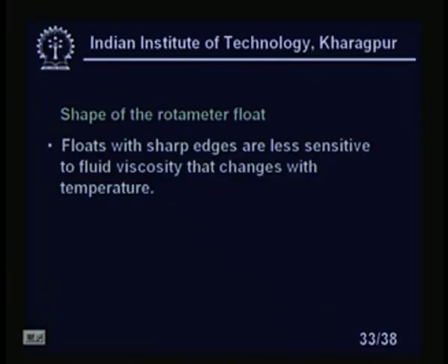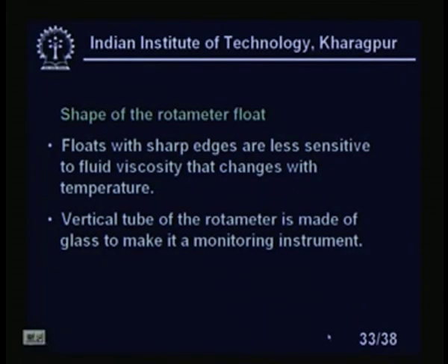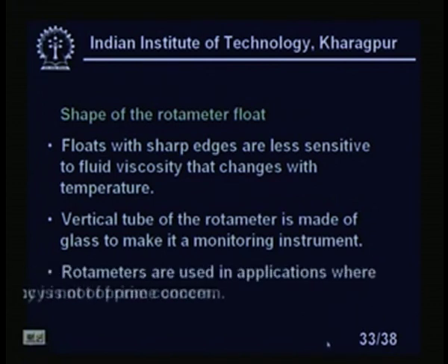Now, floats with sharp edges are less sensitive to fluid viscosity that changes with temperature, right. Viscosity of the liquid, as you know, changes with temperature. But if I make the float with sharp edges, it will be almost independent of viscosity. The vertical tube of the rotameter is made of glass to make it a monitoring instrument.